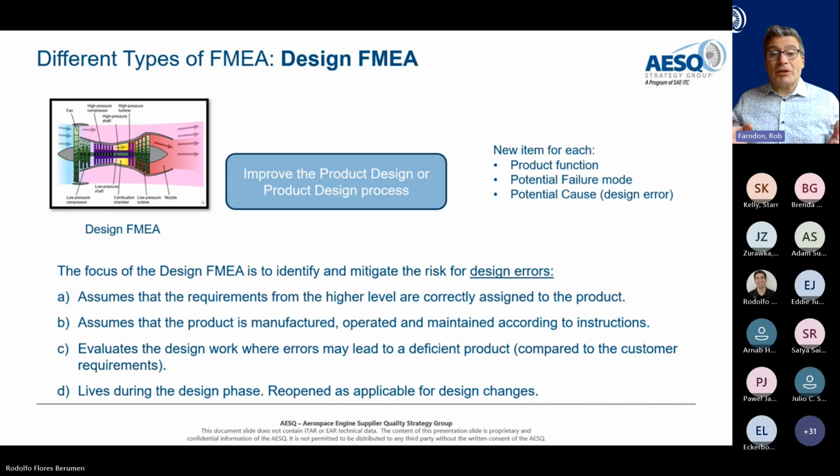This is a tool that we're going to use during the design phase predominantly. While we're actively designing something, we should be keeping the DFMEA up to date and using the DFMEA as a means of improving the design or our verification activities. So really, that's its main purpose and place within the overall process.